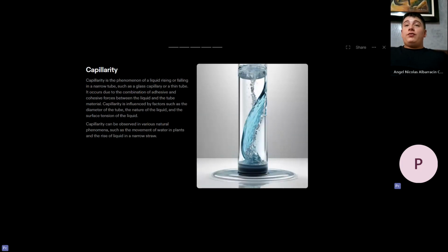That is the capillarity of the fluid. Capillarity refers to the ability of a liquid to flow in narrow spaces without the assistance or even in opposition to external forces like gravity. This phenomenon is particularly seen in non-compressible fluids like water, where it allows water to move forward through narrow tubes, such as tiny vessels in plants, due to the combined effects of adhesive and cohesive forces.